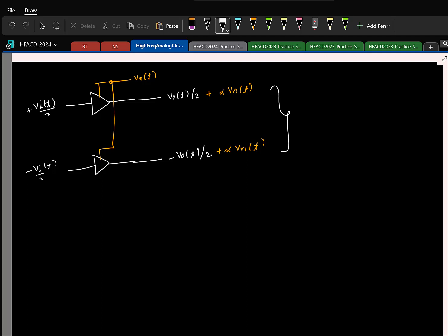So that is why in practice all analog and mixed signal circuits on chip are realized like this as a differential circuit. The only place where you will find single-ended output implementations is where you want to interface to the real world. For example, if you want to sense a signal from a sensor, typically it might give a single-ended output.